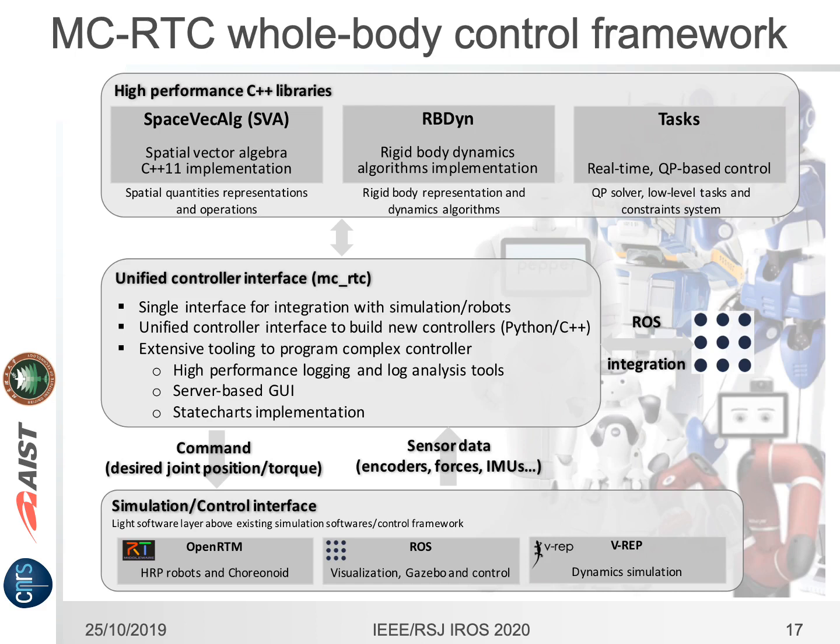Theoretical and technical developments of the previously described controller are gathered into a framework we named MC-RTC. This framework integrates all the necessary components and computations to automatically build the QP control problem from task specification, robots' URDF models, etc. The controller is then made to be interchangeably connected with the robots to be controlled or existing simulators such as Choreonoid, VREP, and recently AGX from Algoryx.